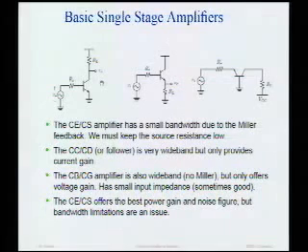So even if we don't have a limitation coming from the source, from the load we have output capacitance, and that produces a pole with that load resistance. So that's bandwidth reduction. And you're precisely right. If I want to get high gain, I need to use either a lot of current to get lots of transconductance, or I need to use a large resistor. And if I use a large resistor, that's going to reduce the amount of swing I have at the output,